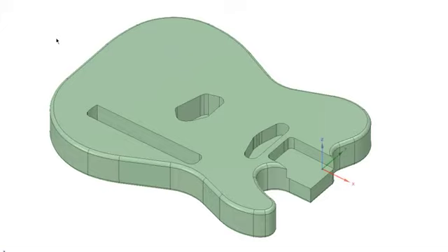And again, it really depends on how close you want to follow the mesh, because a manufactured part is actually an imperfect part, and when you reverse engineer, you're trying to create a perfect part from that imperfect part. So there are many times where I deviate from what the actual scan is, because I'm inferring what my design intent is to the object.